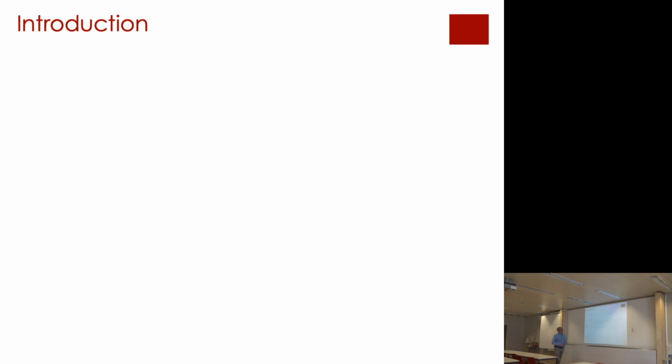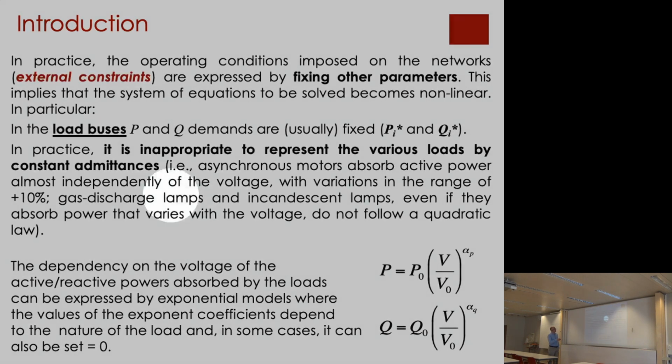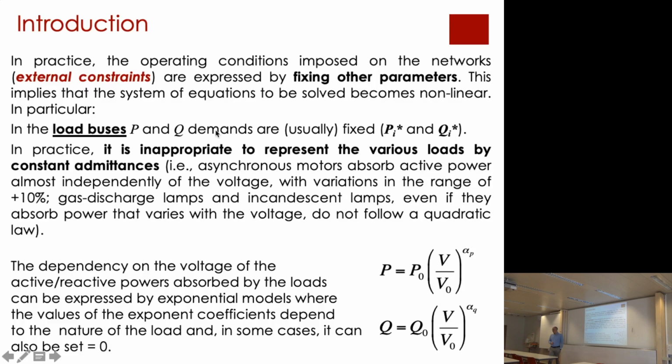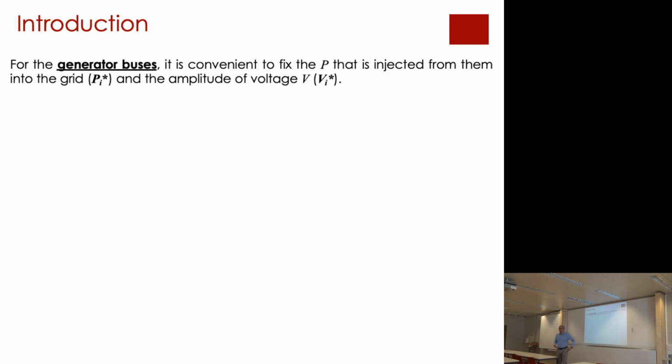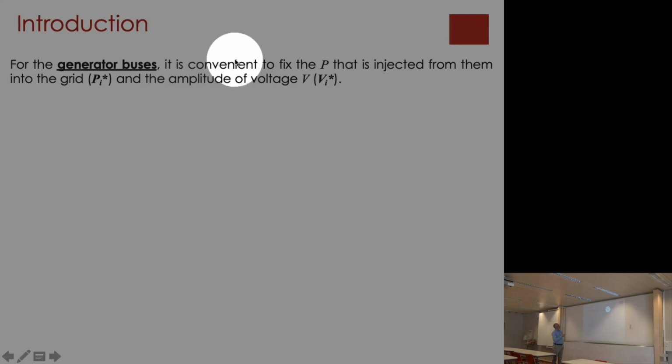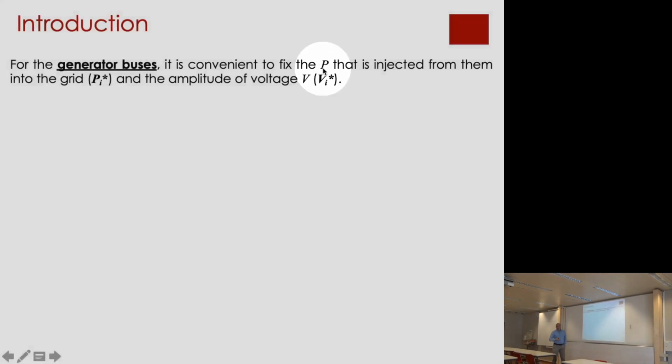So to recap, in the load buses, we fix active and reactive power. Okay? What do we do in the generator buses? So in the buses where you have something which is injecting power, normally in these buses, you fix the active power.